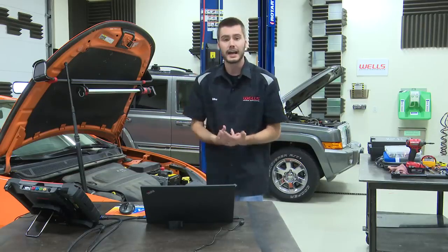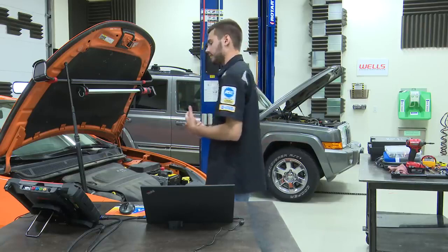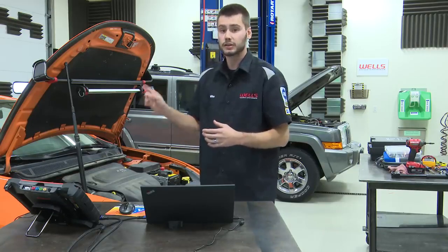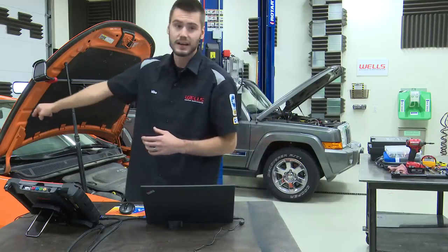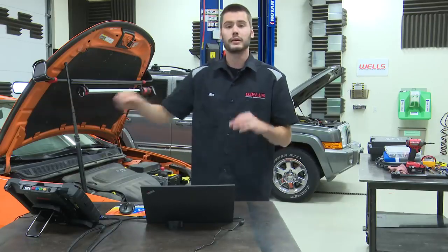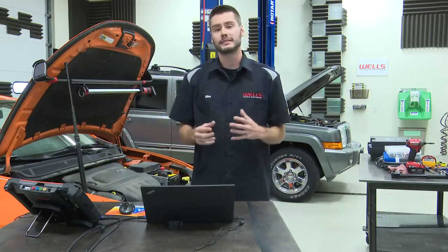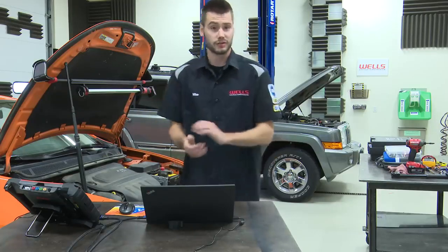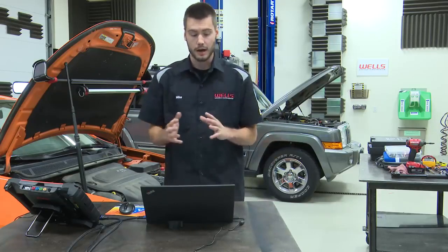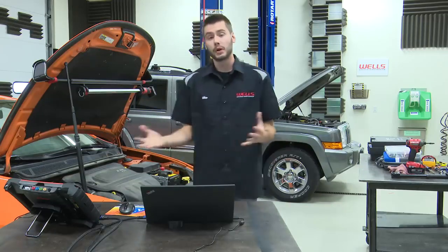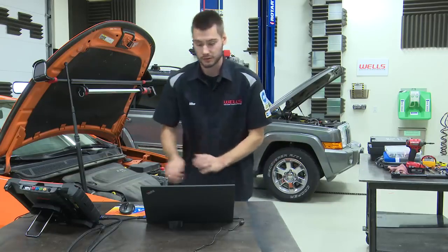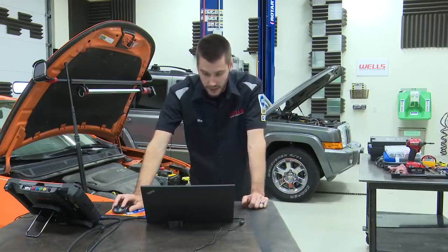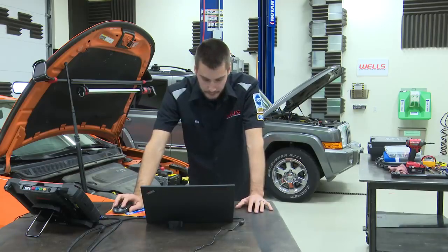This thing has not had any parts thrown at it. These things are kind of known for a lot of issues with modules. The transmission control module actually sits on the passenger footwell, right about where the passenger's wet boots are going to sit every winter, soaks through the carpet right on top of that transmission control module. So thankfully nobody shotgunned that part at it. This thing has had no parts thrown at it besides a reflash so far. So just keep that in mind.